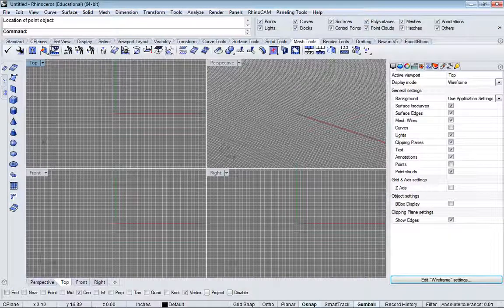So once you start to develop a solid, if you want to render it or transfer it to another rendering software or transfer it to another piece of software, some software utilizes and understands NURBS, but a lot of them do not. So you have to change it and put it in as a mesh. And so basically what you're doing is transforming that surface and approximating those surfaces into polygons. Okay? And so then it becomes static and it becomes faceted in a way. So there's an extensive set of tools to create meshes and to modify meshes.